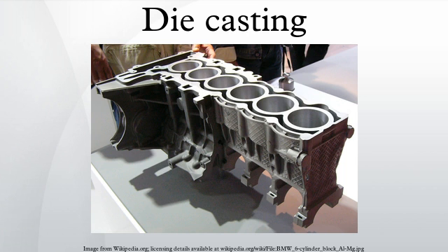Mold or tooling. Two dies are used in die casting. One is called the cover die half, and the other the ejector die half. Where they meet is called the parting line. The cover die contains the sprue or shot hole, which allows the molten metal to flow into the dies. This feature matches up with the injector nozzle on the hot chamber machines or the shot chamber in the cold chamber machines. The ejector die contains the ejector pins and usually the runner, which is the path from the sprue or shot hole to the mold cavity.